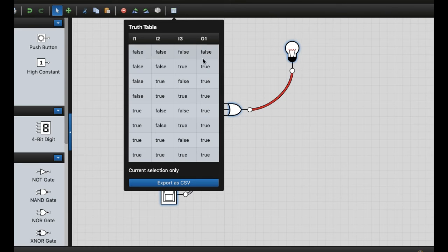And also another thing, when you are drawing the truth table, please remember that if you have 3 variables, 1, 2, 3, or A, B, C, the last one is changing like false, true, false, true, false, true, false, true. If you are representing this using zeros and ones, it is changing 0 1 0 1 0 1 0 1. The second one, double zero double one, double zero double one. The third one, 4 zeros 4 ones.